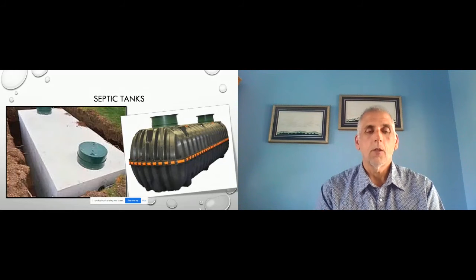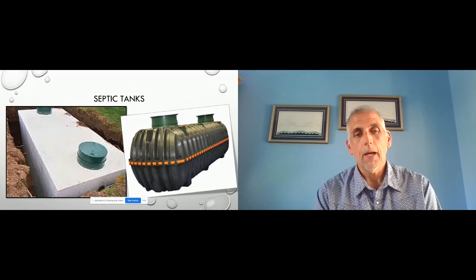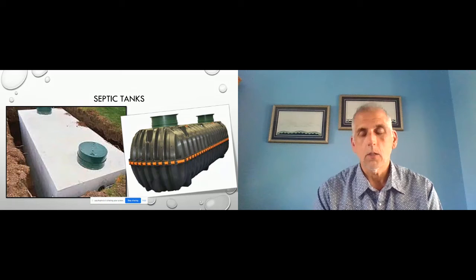Septic tanks have changed over time. When we first started, they were built in place, so you had a lot of block tanks built in the hole that are still there. We still see those on a regular basis on these old sites. Then it went into concrete tanks that are usually two pieces, which may be mid-seam or top seam. And now we're seeing a lot of plastic tanks. The one on the right is a plastic tank that is being used in a number of places. There are some counties in the mountains of North Carolina that haven't seen a concrete tank in 2 years.